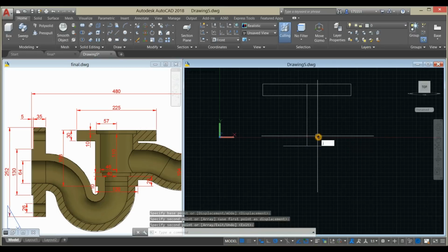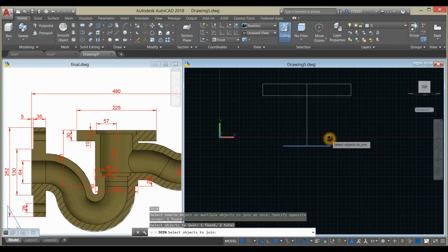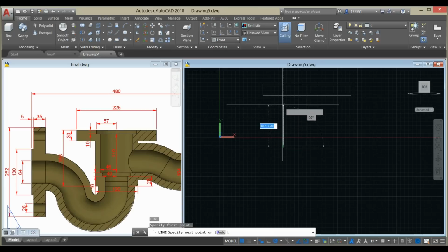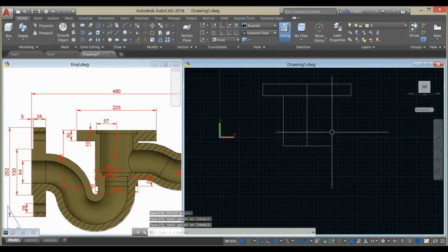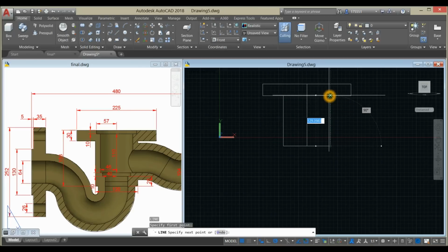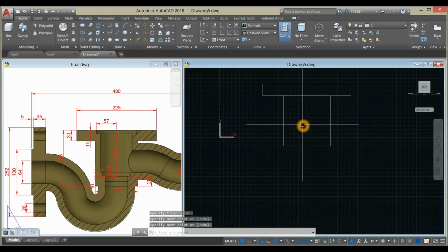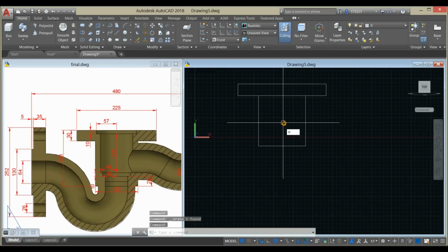I'm going to join these two. I'm just going to double click to check. The length is 120, which is from this point to this point. And alright, so another line from in point, and just hit that intersection line again and click that perpendicular point. Erase this one. I'm just going to trim, so TR for trim command.